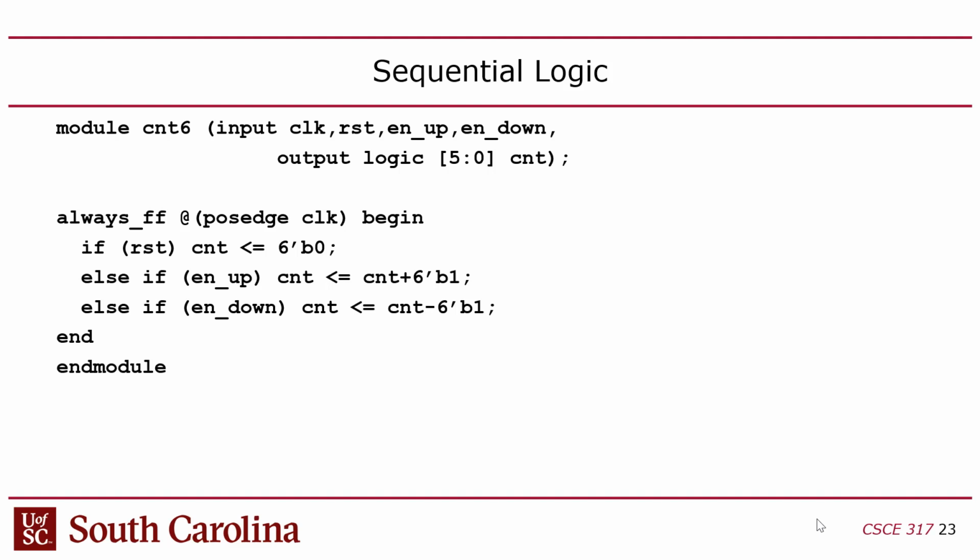So when we build the PWM logic in hardware, you're going to have to take the code that you wrote in Lab 2 and essentially convert it into Verilog, right? Part of that is going to be implementing your own counter, because you don't want to have to rely on the performance counter when you do your hardware PWM. Does that make sense? Okay.